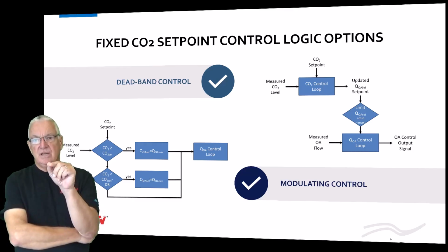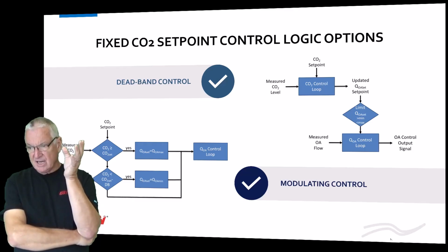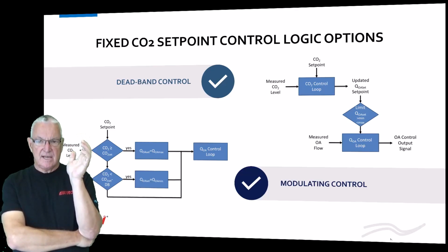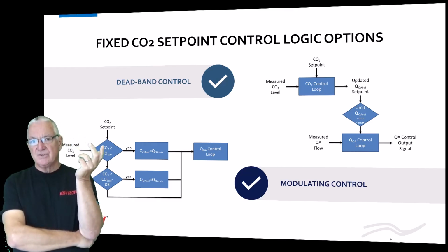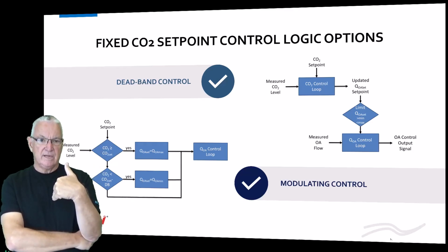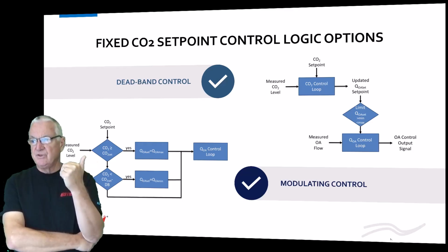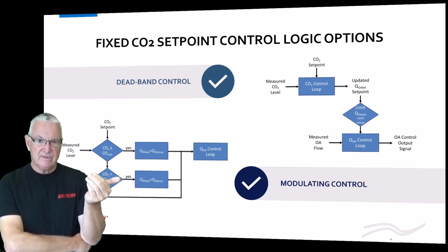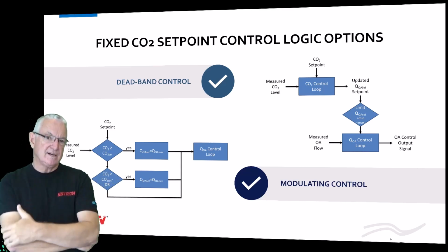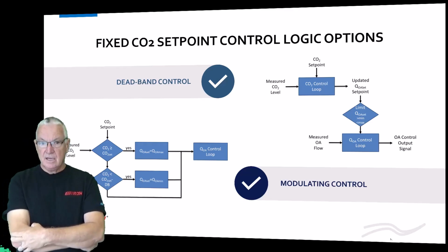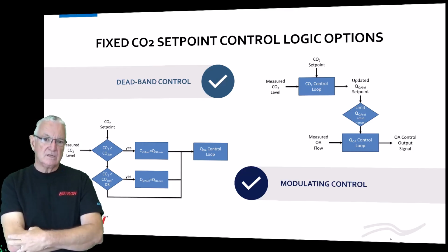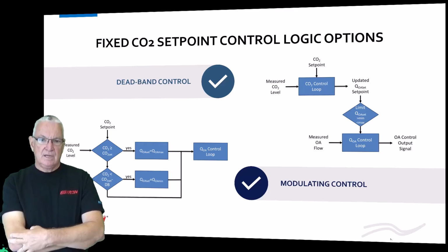Now, the beauty of this, and we haven't talked about IRMM operation yet, is that because you've integrated airflow measurement in it, when you're normally doing DCV, you're doing this modulating control between a min-min and a min-max. But if you got into something like a COVID again, and you said, hey, I want to disable DCV, you basically override the airflow set point. And this works great. You might set it to design, or you might even say, hey, we're off-peak load, we have the ability to even bring in more outdoor air.